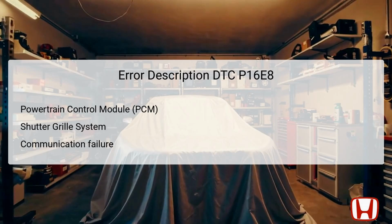DTC P16E8 indicates a LIN, local interconnect network, communication error between the Shutter Grille System and the Powertrain Control Module, abbreviated as PCM. The shutter grille is responsible for adjusting airflow into the engine compartment, which contributes to optimal engine performance and efficiency. Located directly integrated within the front grille assembly, this system relies on precise communication with the PCM to manipulate the shutter's position based on various driving conditions.